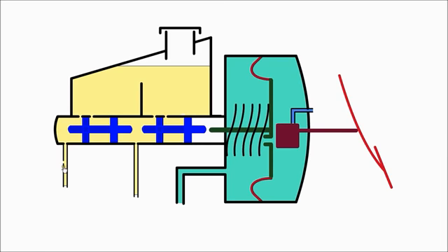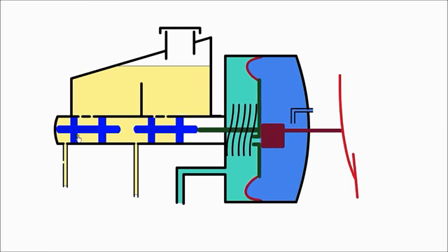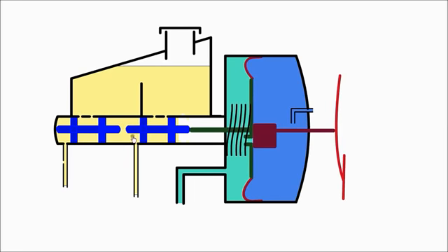If we have a leak in the left-hand circuit, its piston will move all the way to the left, as there is no restriction. The brake pedal will depress further but will eventually build pressure in the other circuit. The division in the plastic storage tank ensures that if we have a leak in one circuit, we will not lose all the fluid in the other circuit.